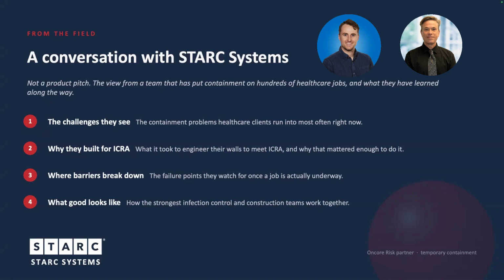But my question to the group and to you is, what do you see some of the biggest challenges that you run into in healthcare right now? What are some of the biggest challenges you hear about, Will? Yeah, some of the biggest challenges I hear about are maintaining a good seal with existing structures. Because as we saw in some photos before, hospital environments are all different. So making sure that a barrier is sealed up against an existing structure is critical.